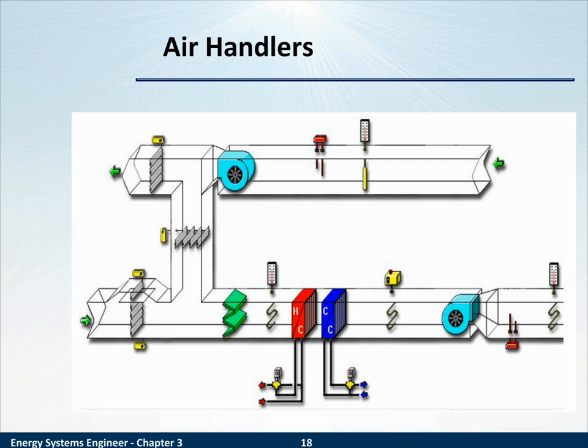As you looked at the previous picture of a heat pump, you saw a fan inside and a fan outside. Here you see more fans. The purpose of these fans is to draw air across the heating coil, across the cooling coil, draw fresh air. It provides the air movement. Note that the air handler is also referred to at times as a fan coil. So you'll probably hear that terminology. But let's look at some components.